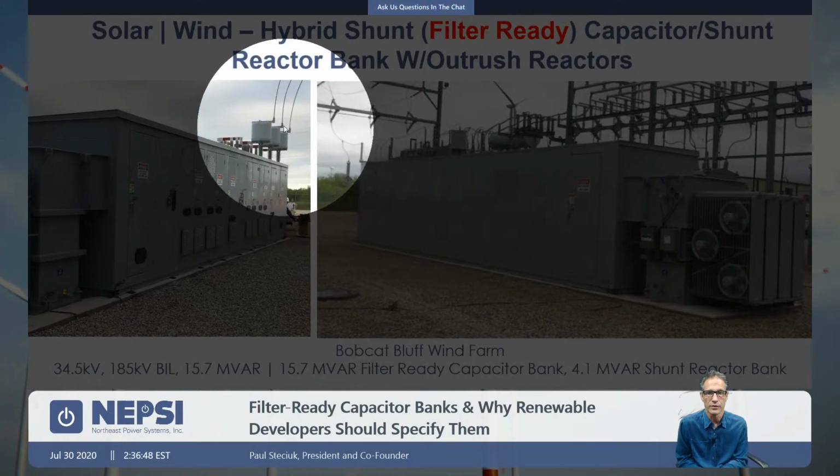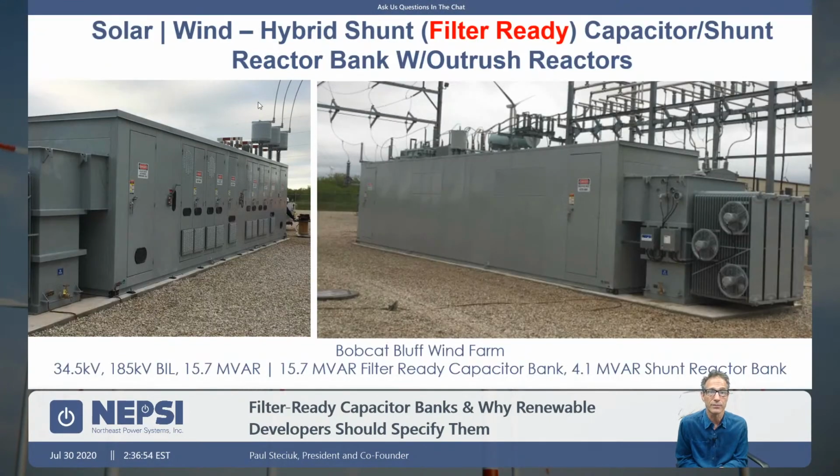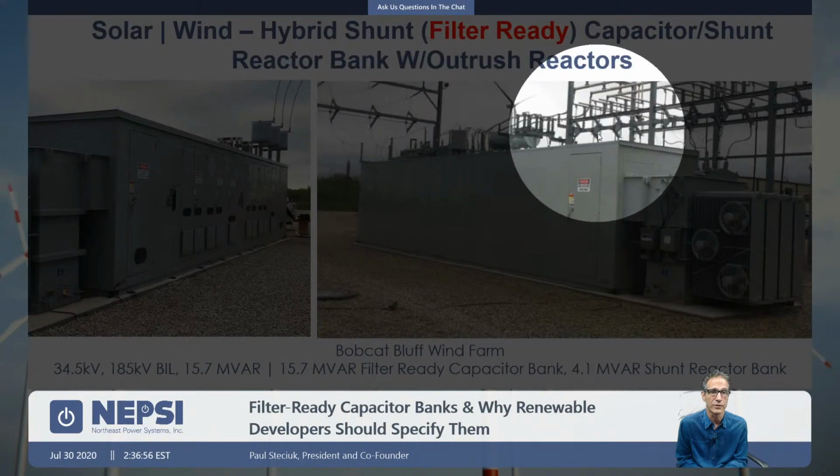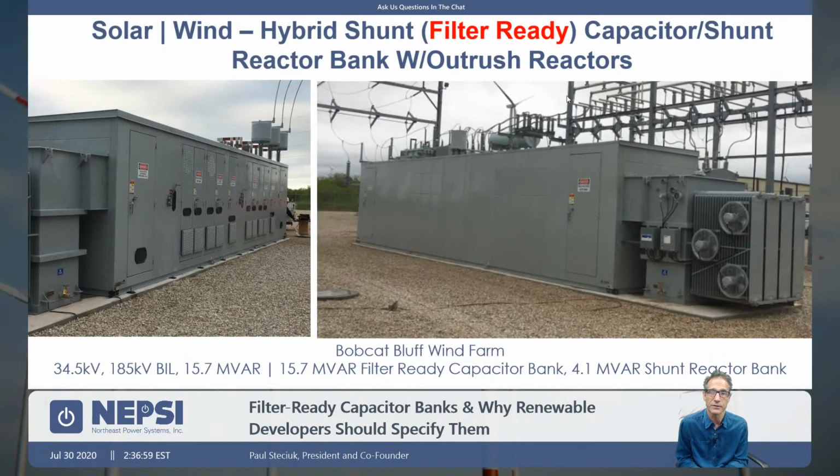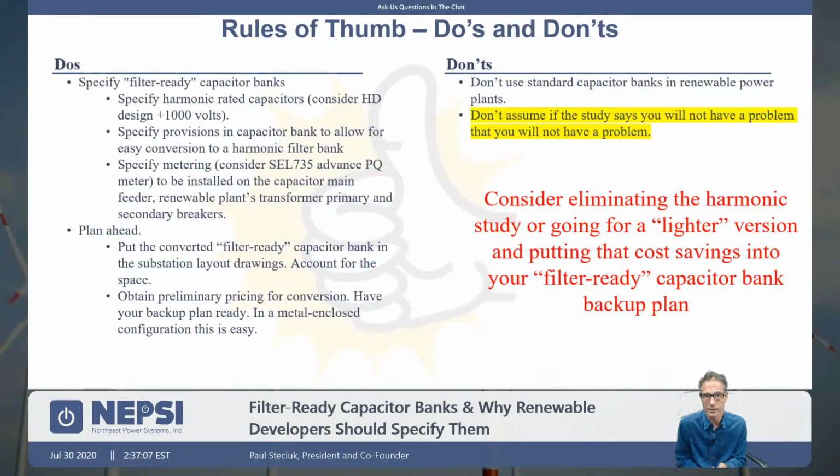The other thing to note is we have some outrush reactors up here. We're limiting outrush reactors here to protect breakers in the substation, the breakers over here. So that will be a tech talk for a future session, is how to size those outrush reactors and why they need to be installed or why they might not need to be installed.